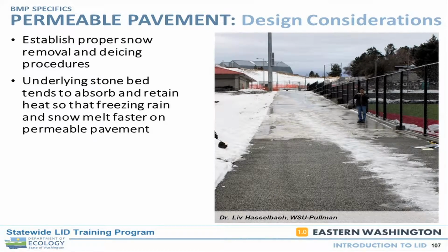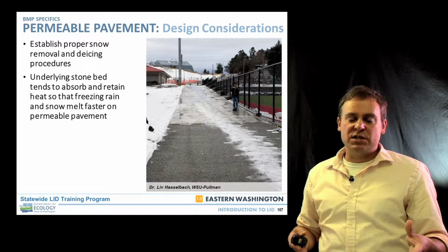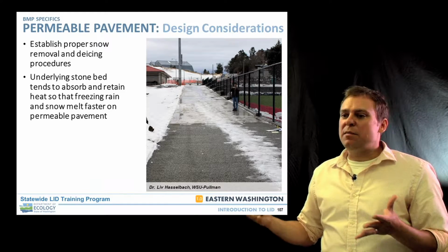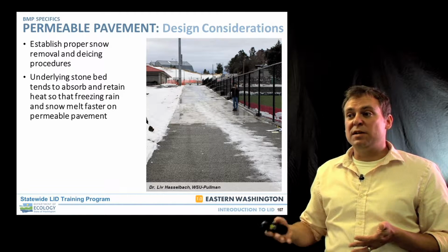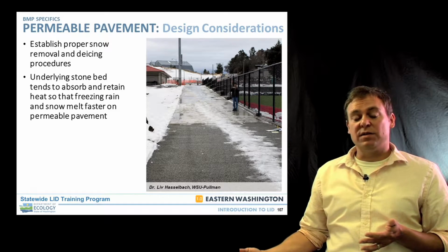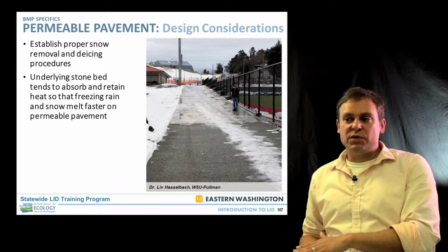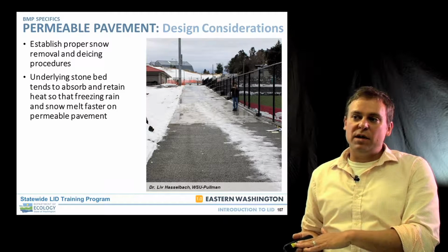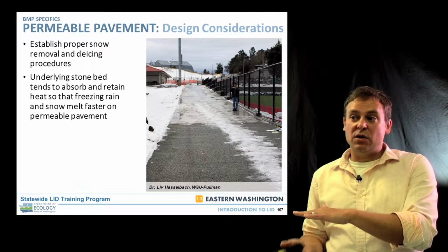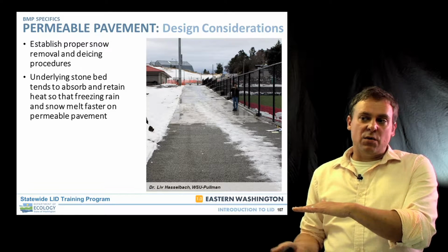Other design considerations, establishing proper snow removal and de-icing procedures. I know that's often a very key consideration for pervious pavement and it'll oftentimes be considered a limitation. And I would say it's both a negative and a positive, really. What's good about porous pavements is that they don't ice up as much, because once it becomes a liquid phase, it infiltrates and gets down into the soils. And oftentimes, because you're designing the systems to infiltrate and provide storage before it infiltrates, that surface that you're on, the native soil surface, is below the frost layer. But if you're in a heavy frost zone, you do need to extend the bottom of the porous pavement subgrade to be below that frost level, because you don't want that freezing up down there.